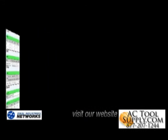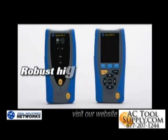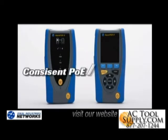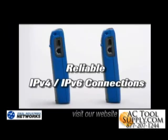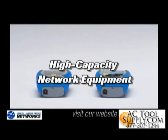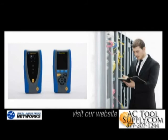Now, in summary, the SIGNALTEK 2 allows me to test and troubleshoot the critical infrastructure components needed to support this high bandwidth installation. That's including the cabling itself, to make sure it supports, say, Gigabit Ethernet. We also want to make sure we have consistent power for our power over Ethernet devices. And we'd like to be able to reliably look at those IP version 4 and IP version 6 connections. And then lastly, check to make sure our high-capacity network equipment can actually support this system we'd like to install. Now, I encourage you to use the SIGNALTEK 2 tester on your next installation, and I think you'll confidently test and troubleshoot your critical network infrastructure.